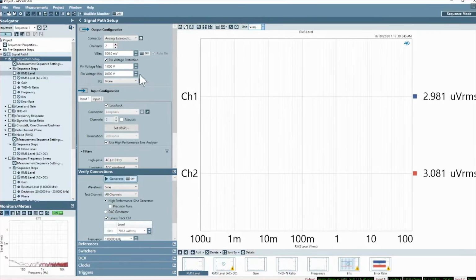Okay, if that did not satisfy the questioner, please feel free to follow up with another chat and we can address that as well. So finishing up here, where's the application for common mode DC? The reason we call it ADC test is that this arises primarily in the case where we're testing ADCs that are designed to be interfaced directly to something like an electret microphone, where there's going to be a DC bias present, and we want to essentially simulate that.